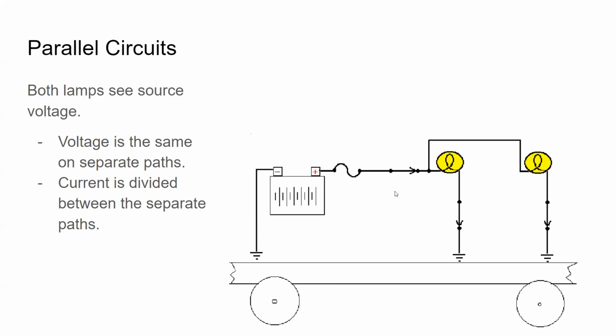So moving on, this is something a little bit different. Most cars have 2 headlights, right? So here's an example of a car with 2 lights on it. This is known as a parallel circuit. We've got 2 circuits here. Besides this connection that jumps over to the other side of the car, this bulb and its path to ground is the same as this bulb and its path to ground. These are identical. They're moving the same direction. They're parallel. We have our battery, we have our fuse, we have our switch.